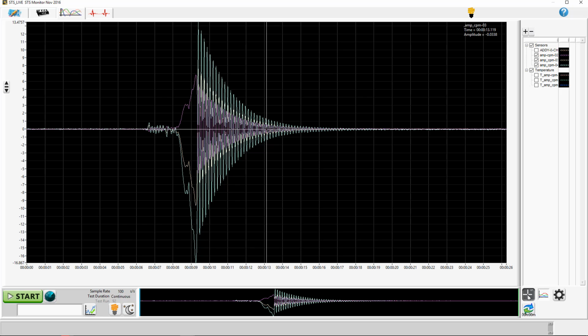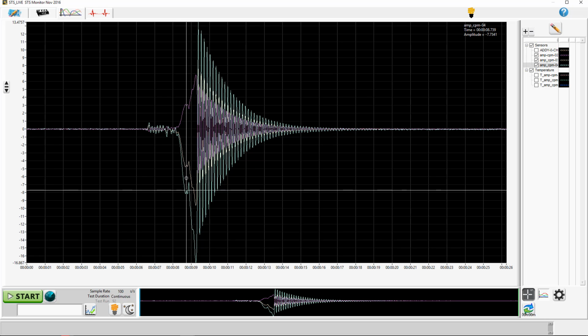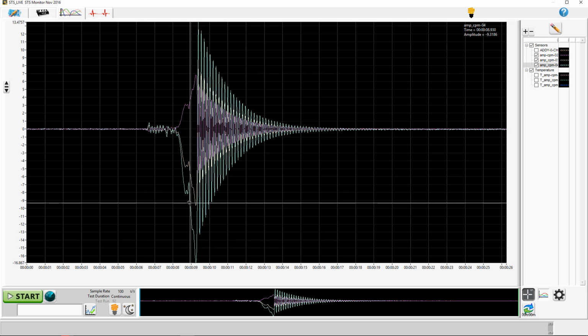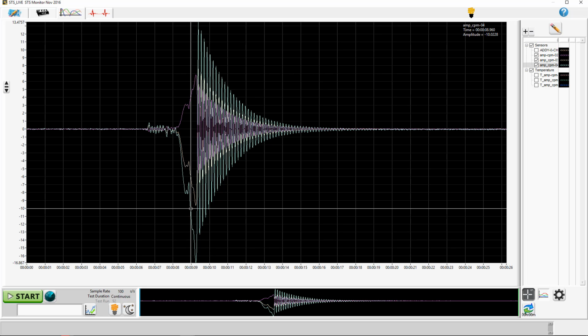We can activate the cursor, select it on the sensor, and move the cursor around. And you see here, these sensors are going negative. Let's say that if we pass -10 micro-E on this sensor, number 4, we want to record an event. I just wrote that down.